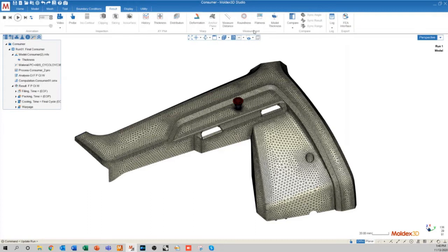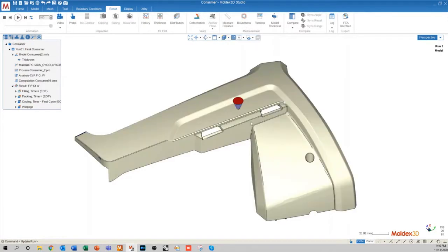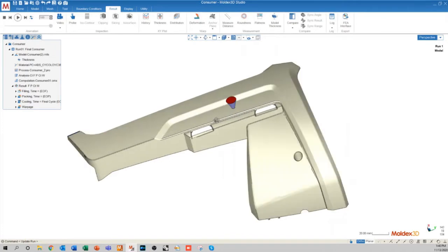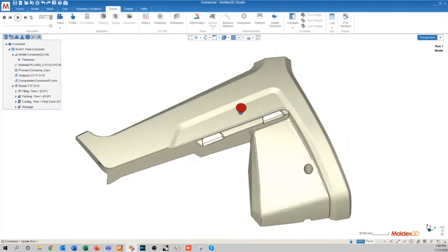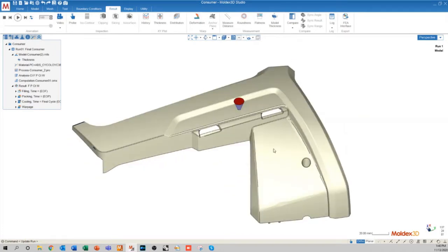There's a little toolbar right at the top middle of our screen. I'm going to go right in the middle of that toolbar, which is the 5th button over. It looks like an orthographic cube. I'm going to click on the drop down and go to the 3rd option, which is show feature lines with shaded faces. All right, and it'll essentially just get rid of our mesh lines while still showing all of our feature lines.